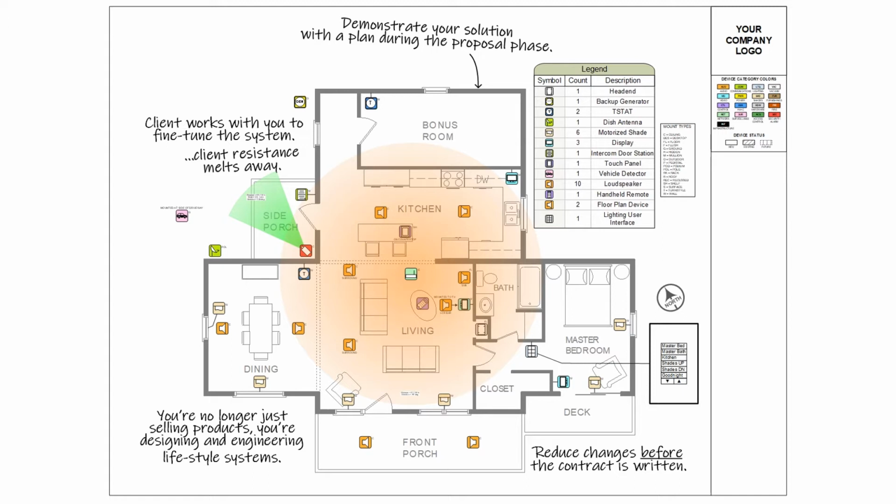We can also show keypad engravings. On the lower right side of the page, we see a lighting keypad with engraving pointing to the lighting keypad symbol location. This can be very useful where the client or lighting designer walks through the plan, checking the engravings and signing off before ordering is done. Additionally, any unique or custom symbol and icon you might need to stand out from the standard symbol library should be simple to create.